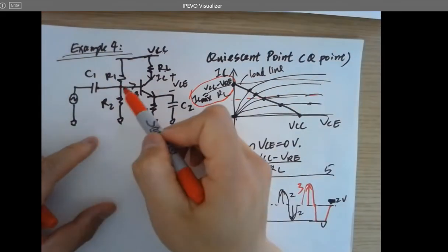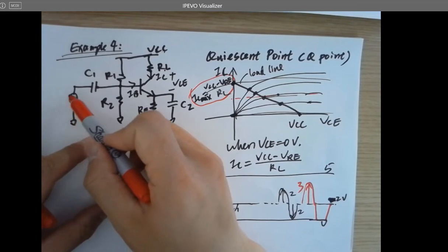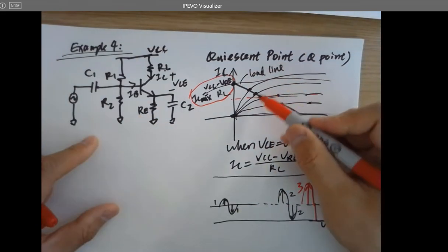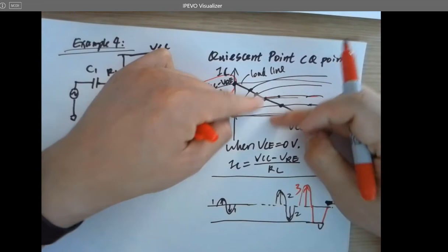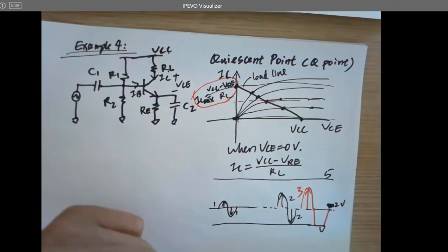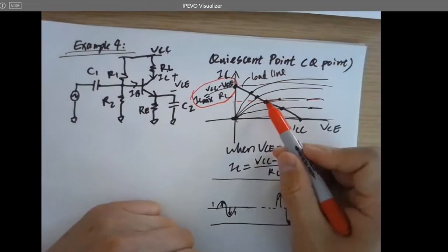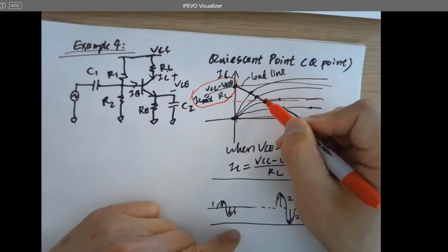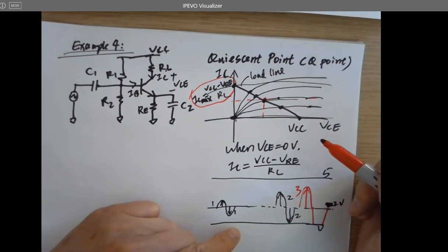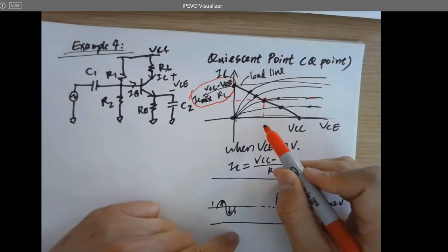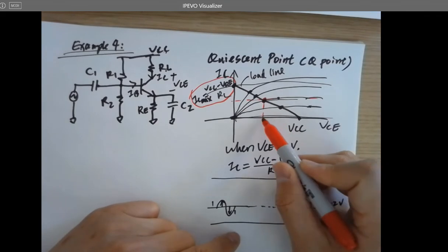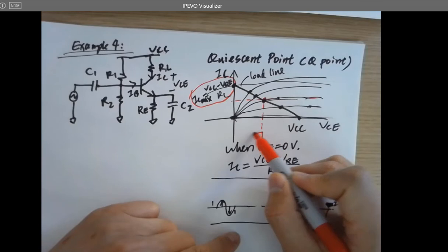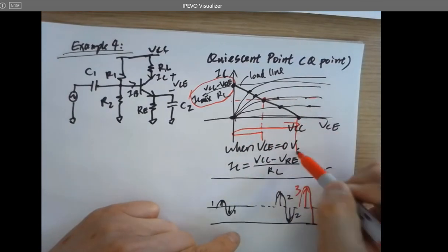When you're amplifying a little signal, like an audio signal, a small input in millivolts, you can get a larger swing on both sides of the range. So if you bias your transistor here, your VCE can swing like this in these 2 ranges.